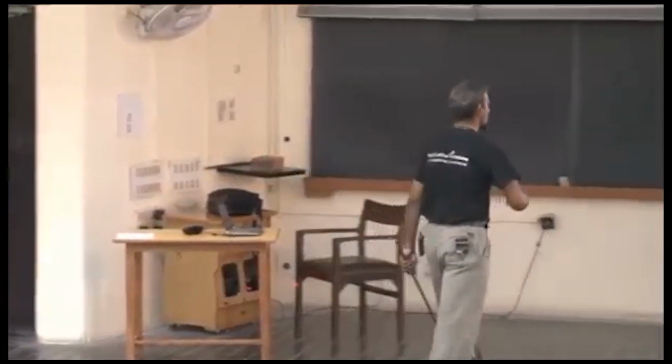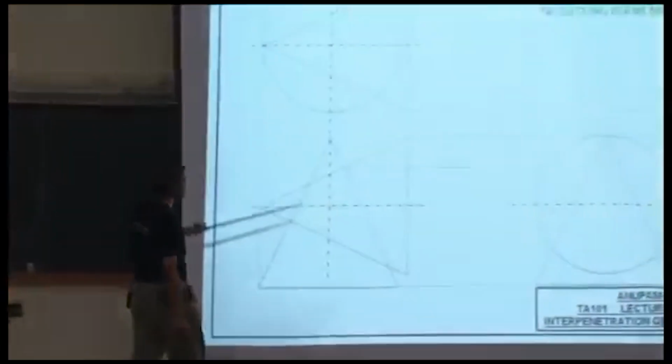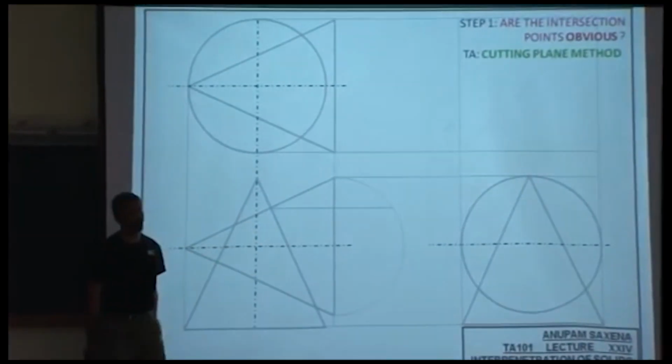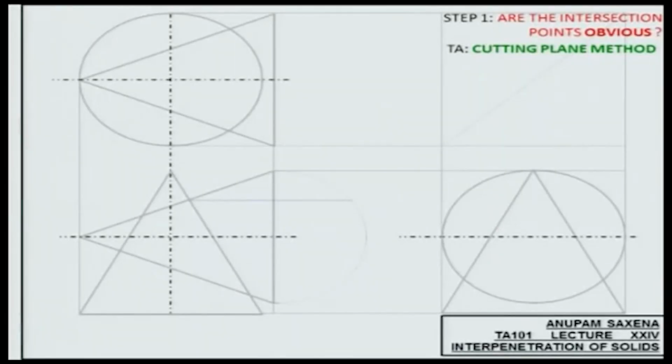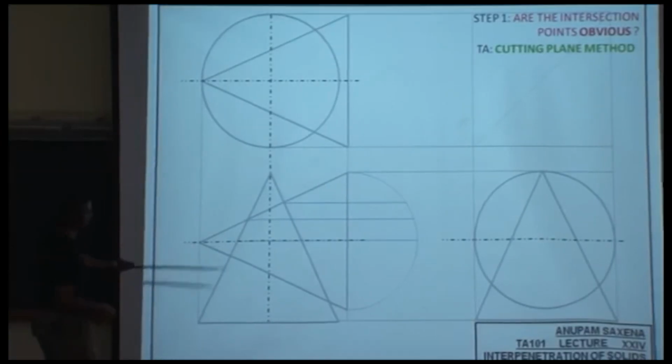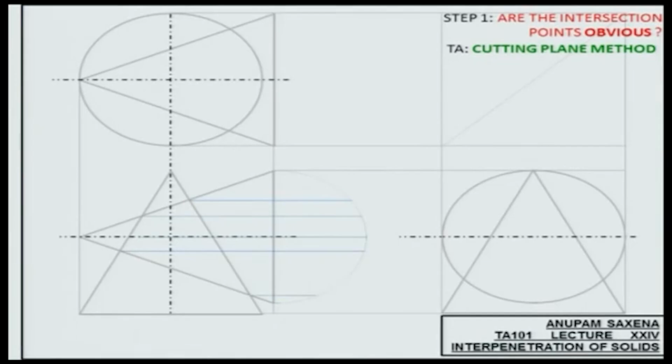For a more accurate solution, you should be using more horizontal planes slicing the assembly of these cones. So the first horizontal plane is this one, second one is this one, third one contains the axis of the horizontal cone, then the fourth one, and the fifth one. Now follow this very carefully because things are going to be a little messy.